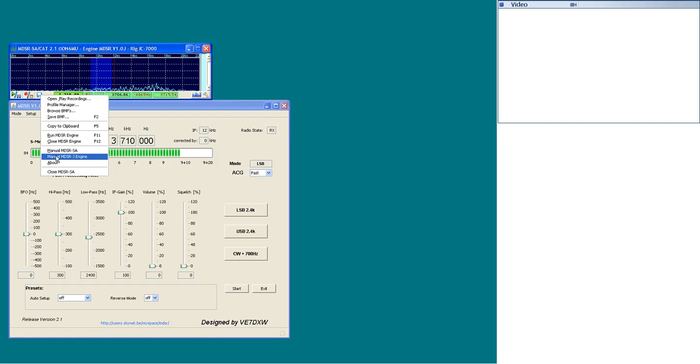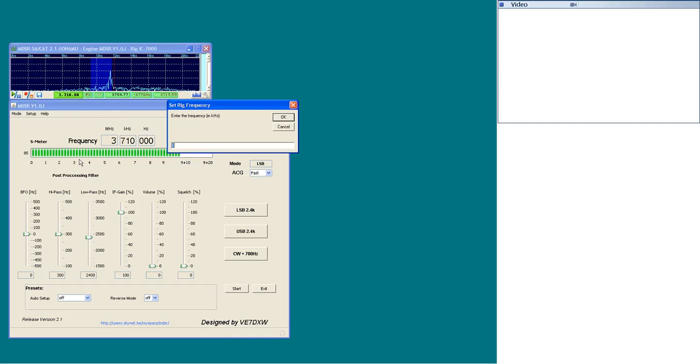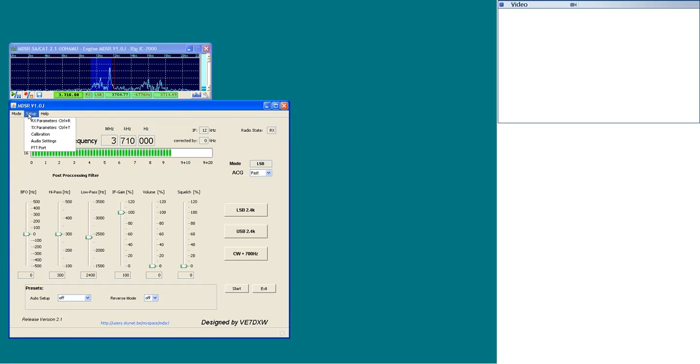The multifunction toolbar provides all the information needed to operate the transceiver from the computer display. The current frequency is displayed on the left side, and clicking on this field will open up the memory frequencies for each band. Clicking on each band selection will set the radio to the frequency that has been configured in the Setup Predefined Frequency window. It is also possible to type in a frequency and send it to the transceiver via CAT control. The Setup Rig selection will bring up the user interface for the OmniRig setup. We will get to that later.